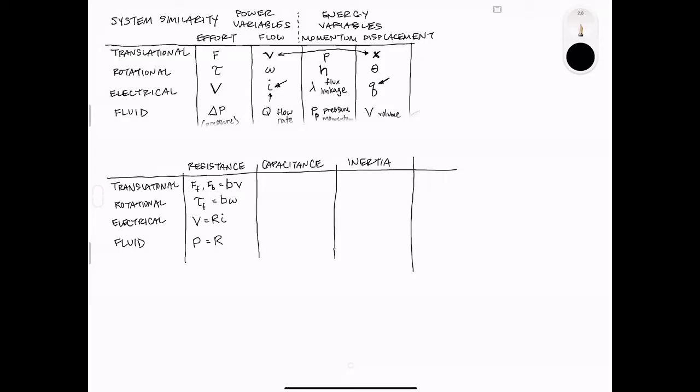That's going to multiply by the flow rate for a component relationship inside a fluid system. Well, let's do for capacitance something in the translational side of things, and that is a spring. So we'll do Fs for spring. Okay, the force in a spring is going to equal K, some sort of constant for that spring, times a displacement variable, X, for the last column up above.